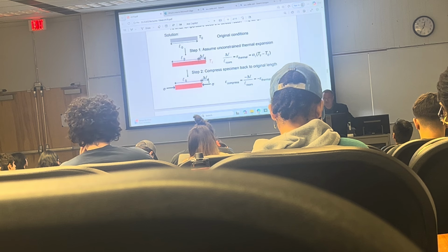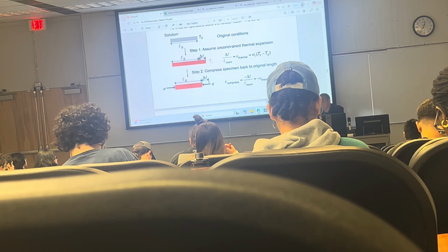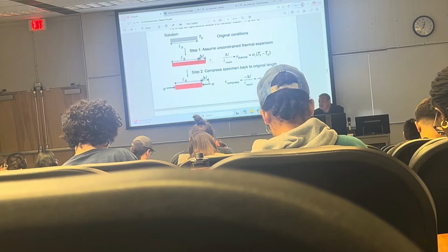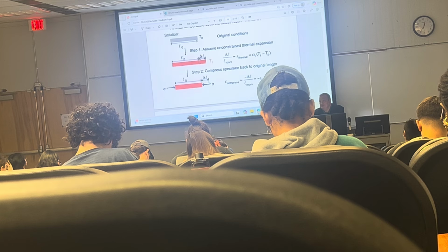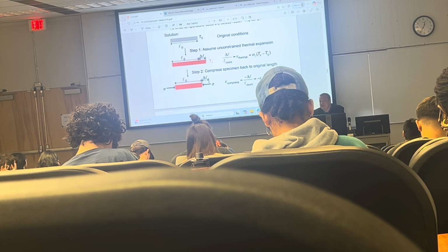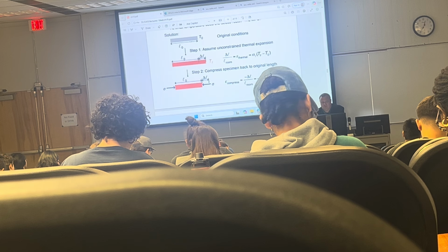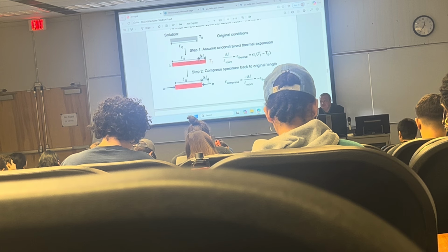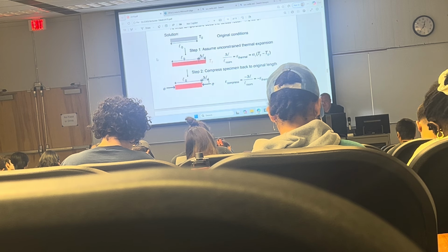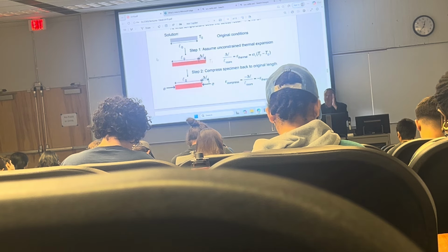All right. So I understand that if you're in industrial, you're not taking mechanics of solids, but this is a trick. Does that make any sense? Okay. In mechanics or in general, this is called a kinematic condition. And statically indeterminate means that we cannot solve it just based on statics. Because you can say that the force or the stress on both sides is equal to the one that's in the material. We cannot separate the forces, so we need another compatibility equation. And the compatibility equation comes from the fact that it does not move.